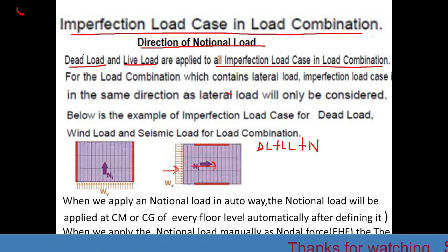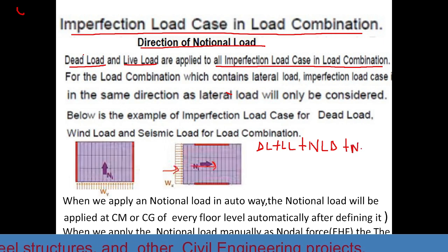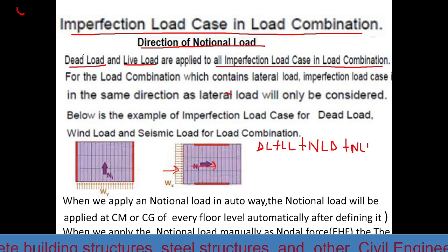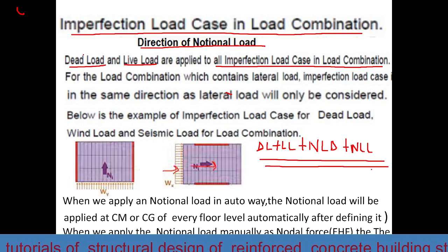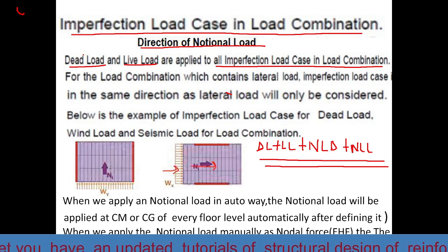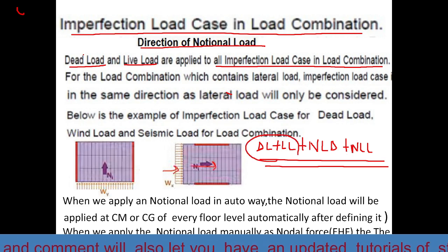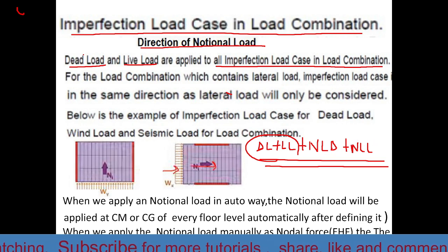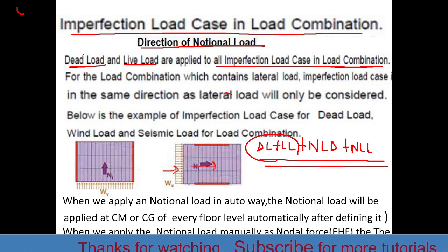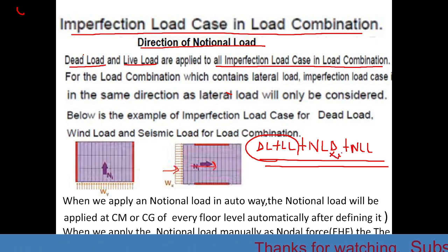That is the notional load dead, plus the notional load live. So this is one of the combinations of the notional load with the gravity load. However, we have to specify its direction. The notional load may be in x or in y direction.